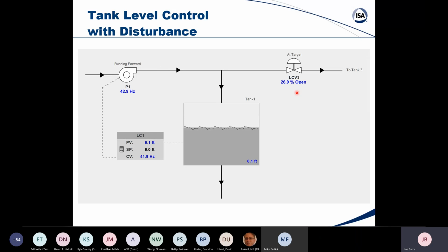So how can we possibly model a process separate from disturbances when they're so interdependent? And the answer is we can consider some baseline constant valve position to be a fundamental part of this process, and only changes in the valve position are disturbances. So we're going to call those baseline conditions our normal operating conditions.